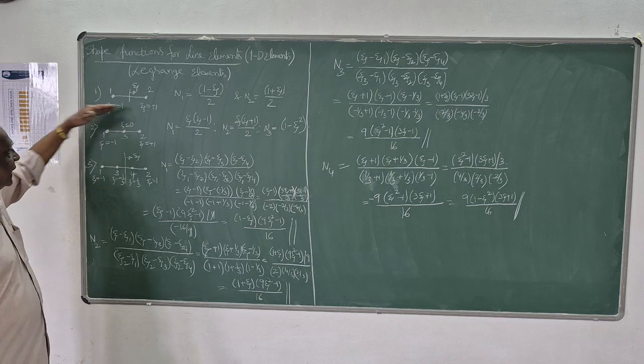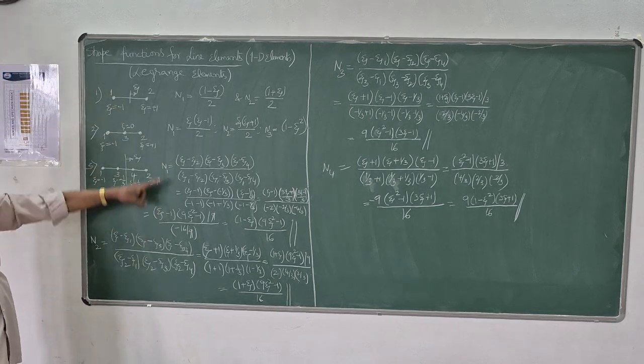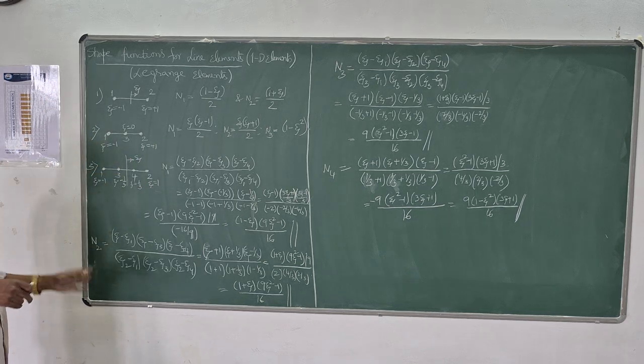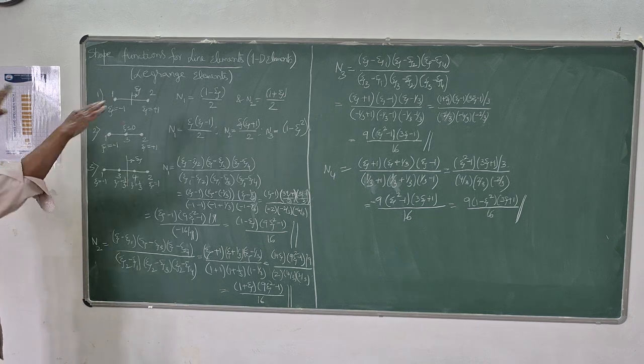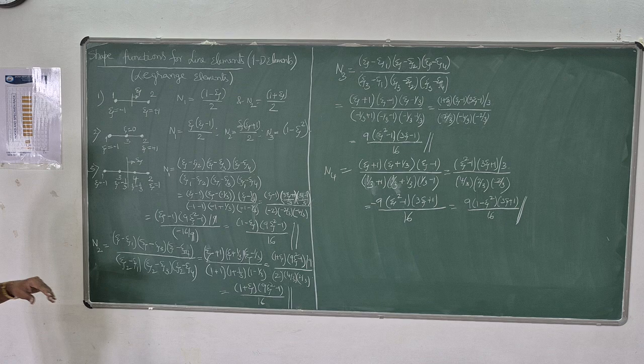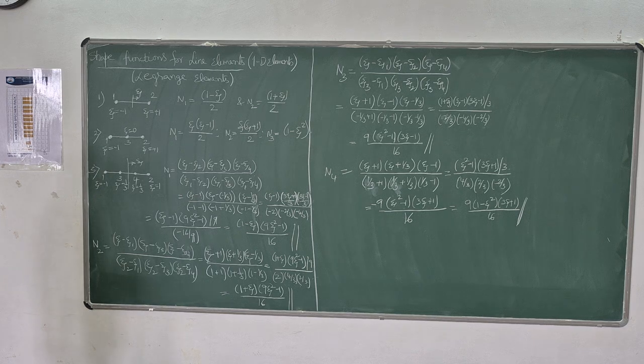If this line lies in the y direction, then replace z by the eta coordinate, and you will get that one. If it is a rectangle, a 2-dimensional figure, find the tensor multiplication of that. That's the simplest procedure for finding the shape function.